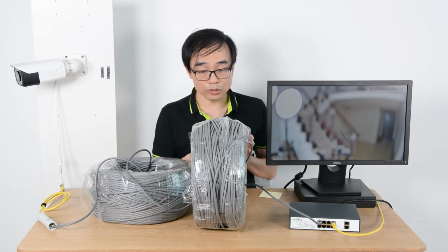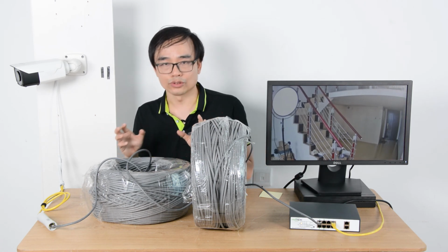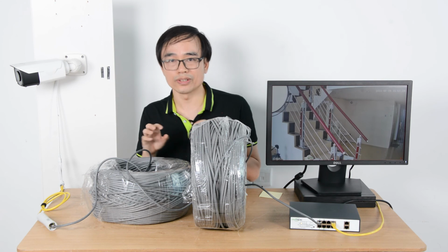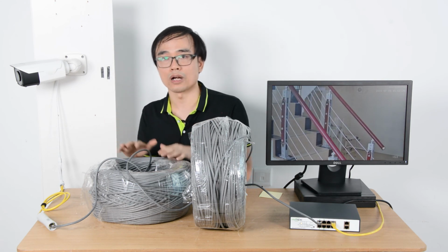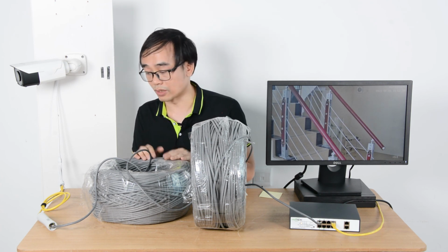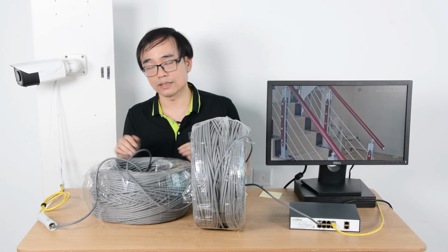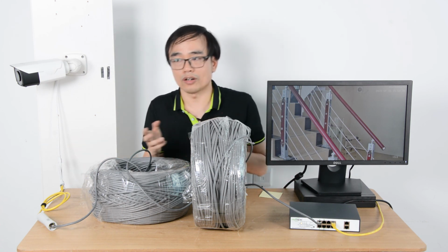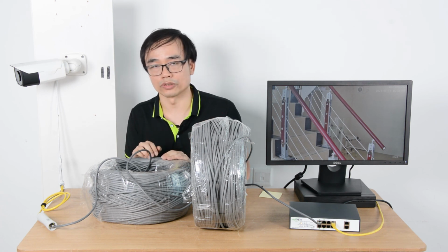When you're sending PoE over ultra-long distance, you should pick pure copper. Even though it's more expensive than CCA, it can reduce the power loss. The bandwidth is really not the problem, because the transmitter, the PoE switch and the adapter will take care of the signal as long as it's a standard cable, but pure copper is very important.